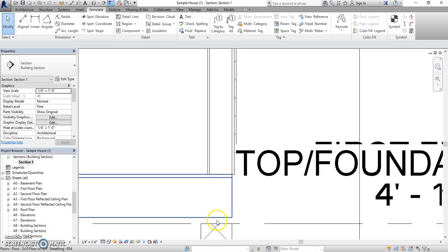I see I left space in here because I need a 1.5 inch sill plate. I'm going to put a 2x8 in here turned flatwise, and a 2x8 has a 1.5 inch height when it's turned flat. I also see that the outside face of my foundation wall, my exterior core face, matches the edge of my floor, and matches the exterior core face of my stud wall above, which is perfect because I'm going to want to run all of this finished stuff, the exterior wall sheathing and the vinyl siding, down below where the wood construction stops and the concrete masonry construction starts, so that all of our elements will trickle down and drop off below the wood construction.